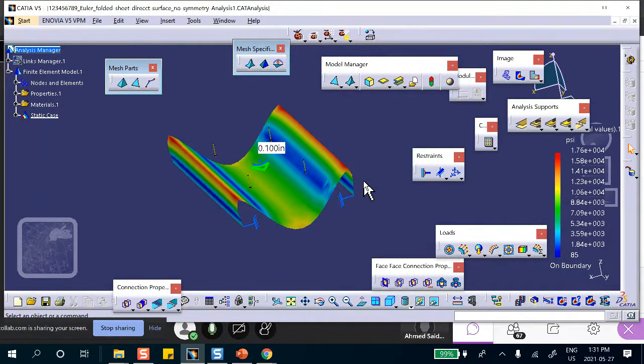No questions. Let me show you something else while we're at it. Remember those stresses in beams we couldn't get? The only thing that you could get in beams was the axial principal stress, which is totally useless. That is not the case in shells. In shells, you can get von Mises stress, and you can get the in-plane principal stresses, the kind of thing that you did in Mohr's circles in your deformable bodies or stress analysis.